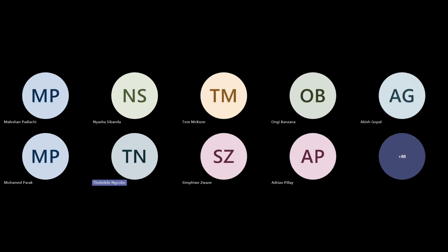Firstly, none of the steel lost its cross-sectional area. As well as the fact that it is a post-tensioned bridge, none of the cables were affected by the fire. And if you recall, I did mention that in the microstructure, the quartz was still present in the concrete matrix, suggesting that the temperatures were below 500 degrees Celsius. And steel will typically lose significant strength at around or above 600 degrees Celsius. So I hope I answered your question.